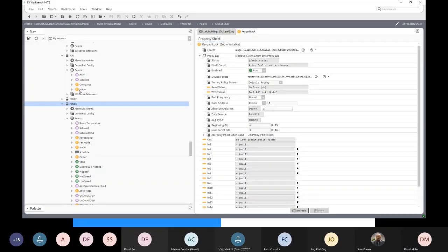Or is there 3 power meters, 2 transfer switches, 5 fan coil units from vendor A, 7 fan coil units from vendor B? Now you're up to 3 or 4 different mapping tables that you have to read, interpret, create. So your job just got 4 times bigger because you've got 4 different devices that you have to integrate into Modbus.